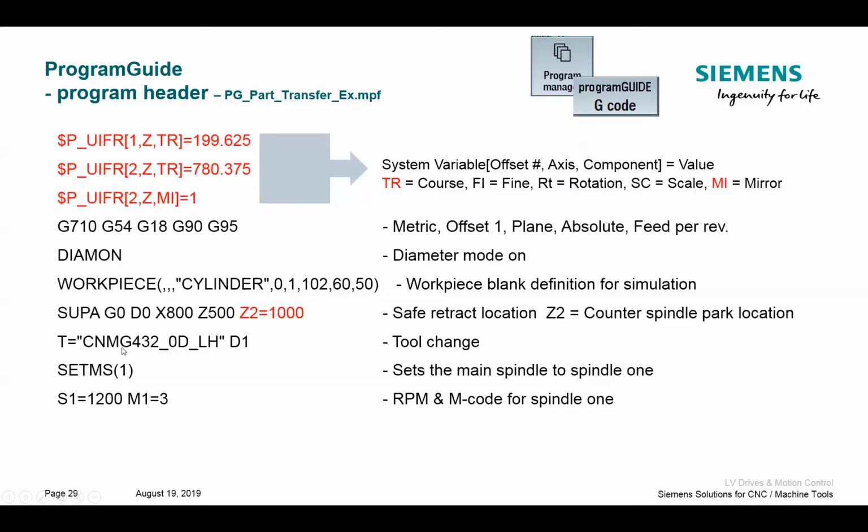That's just assigning the M codes, or what the primary spindle is doing, spinning the work holding. And when you get to multi-spindle machines, you do want to assign the S and M codes to that spindle. So if you just do the set main spindle index 1, you could get away with just typing S1200 and M3 and it would work.